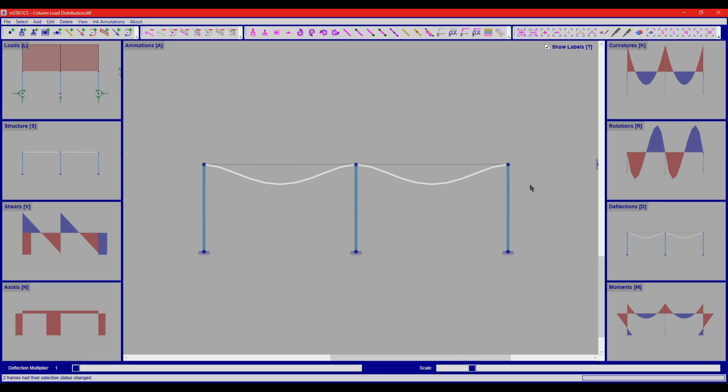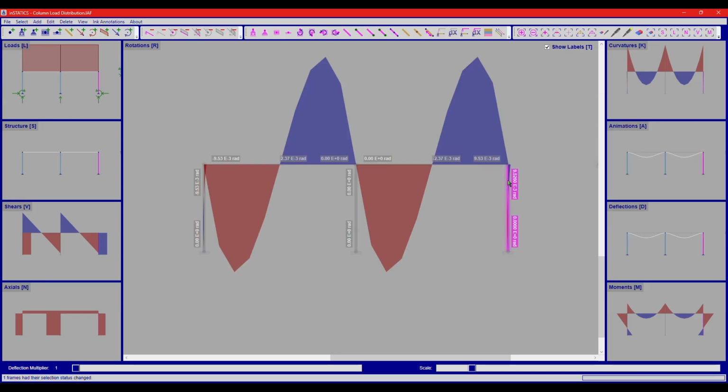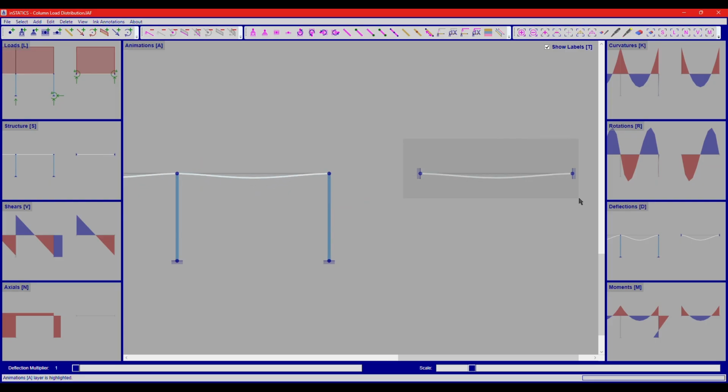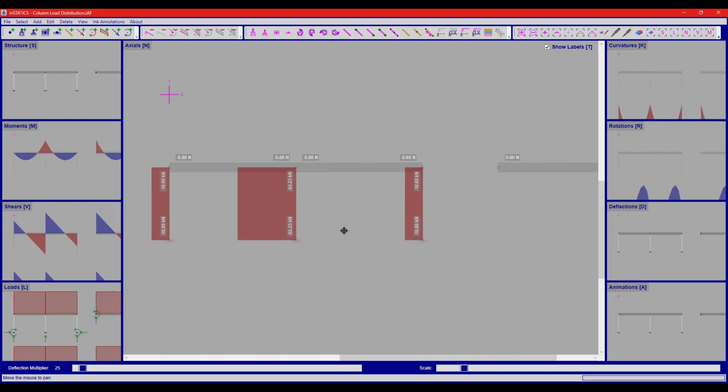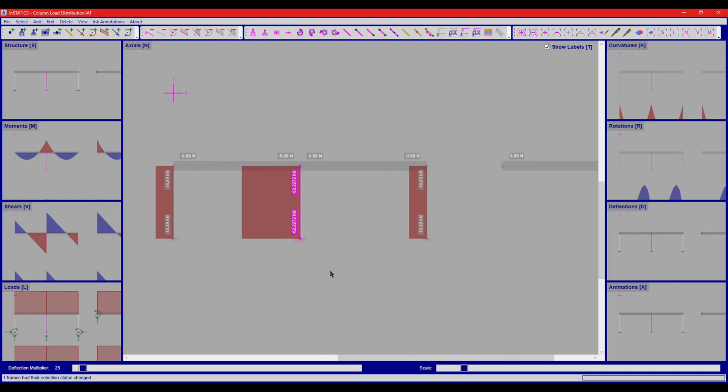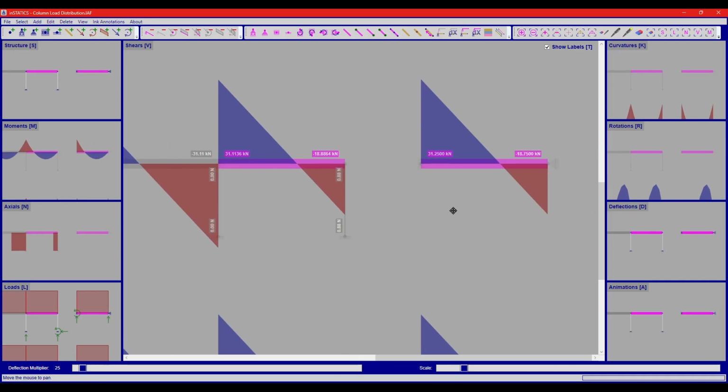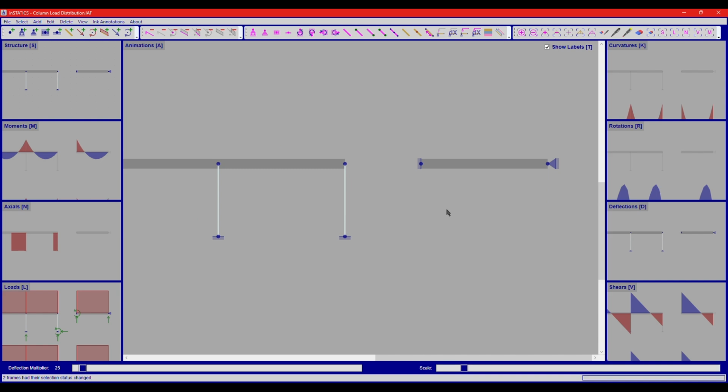If the beams are much softer than the columns in bending, the distribution is similar to a simply supported case. The beams will not be able to rotate the outside columns, which is analogous to a symmetric fixed beam. If the columns are soft and the beams are stiff, then the beams rotate the columns, effectively simulating a fixed pinned scenario where most of the load is transferred to the continuous or fixed end of the beam.